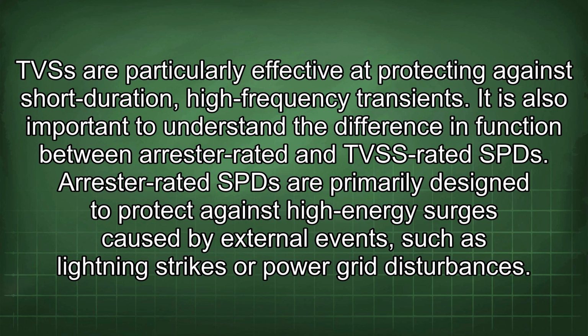It is also important to understand the difference in function between arrestor-rated and TVSS-rated SPDs. Arrestor-rated SPDs are primarily designed to protect against high-energy surges caused by external events such as lightning strikes or power grid disturbances.